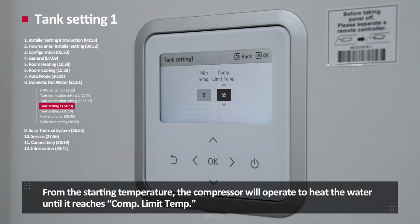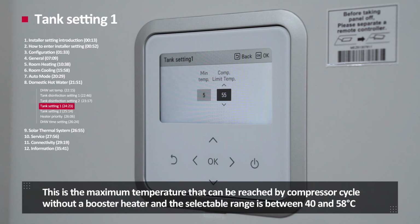From the starting temperature, the compressor will operate to heat the water until it reaches comp limit temperature. This is the maximum temperature that can be reached by a compressor cycle without a booster heater, and the selectable range is between 40 and 58 degrees Celsius.